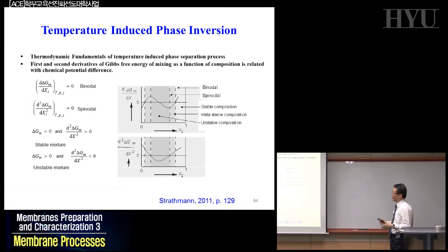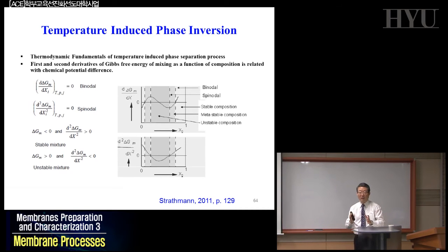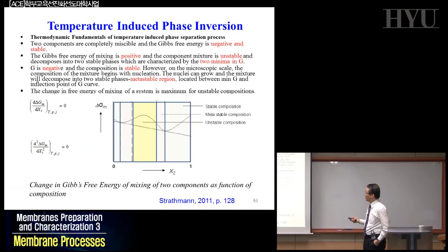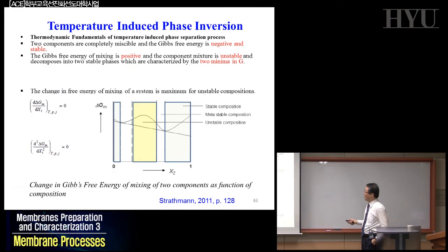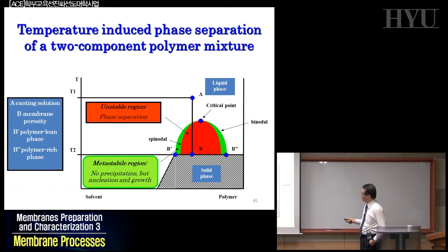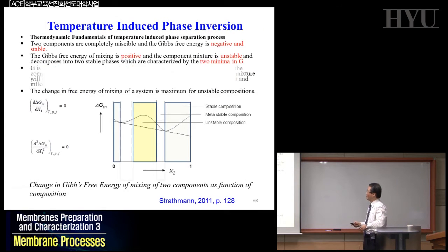And this way, you will be able to define and describe, theoretically, thermodynamically, the spinodal points and binodal points. So again, if you go back, this point is the spinodal or the binodal point. This is the spinodal point. And again, we can take a look at the temperature versus the composition curve. This is the binodal point. This is the spinodal line, as you have already seen.